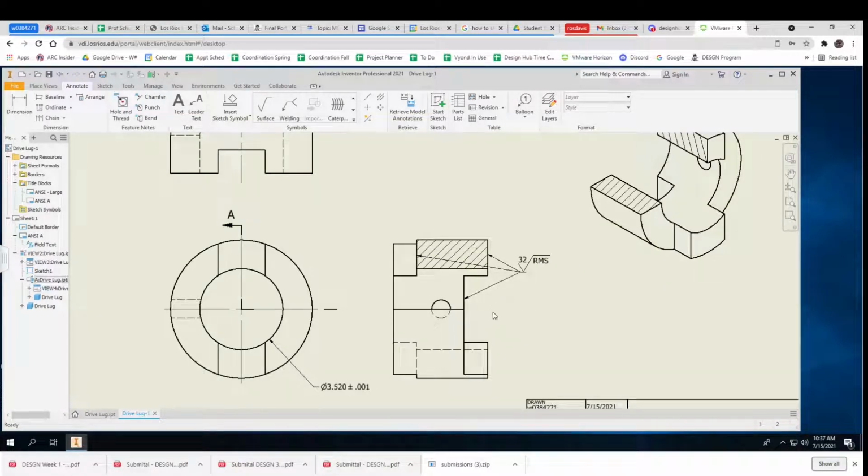I mean, if anything is on there, that's where they would be. Now, what was your tolerance that you put in there, that 32? 32 surface finish: is there any ridge or extension above a perfectly flat plane that is more than 32 microns?